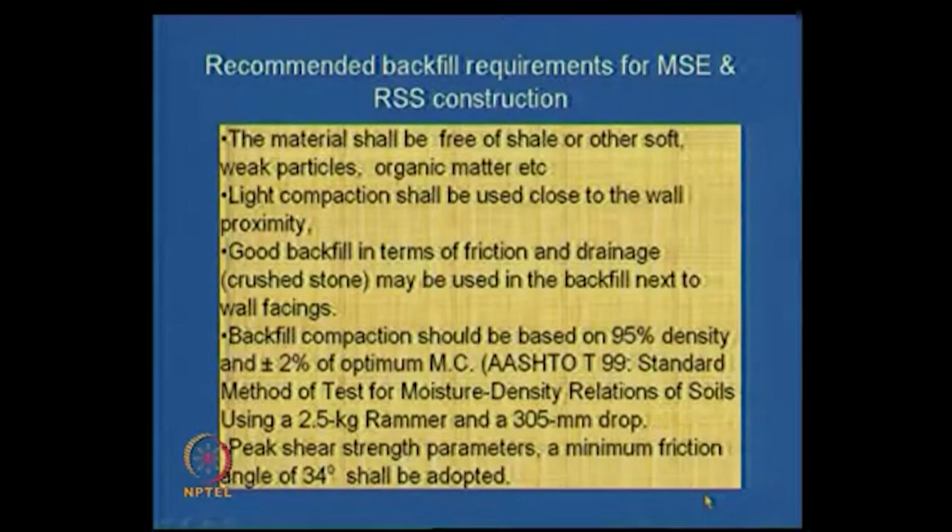Something more important: the backfill material should be free of shale or other soft materials, weak particles, or organic matter, because the backfill should not get degraded or become soft. Some materials like talc, if they become saturated, may become a little soft. So, we do not want that.